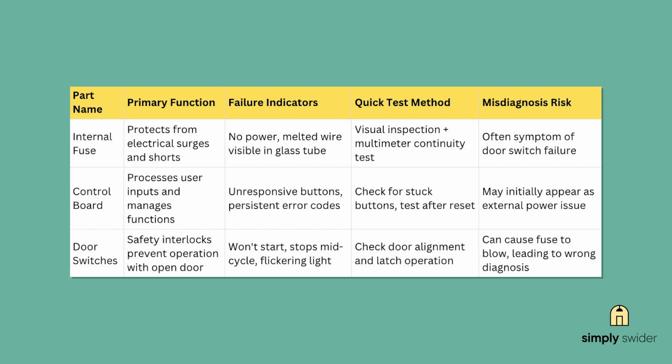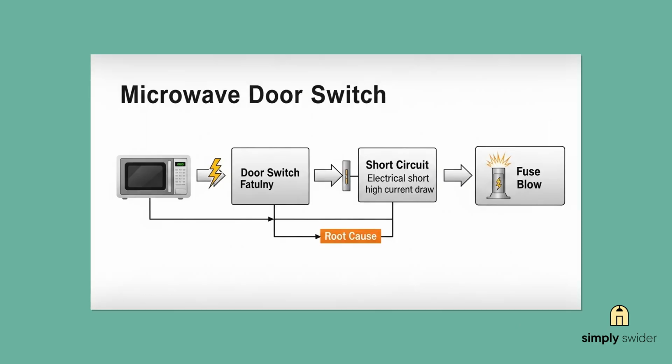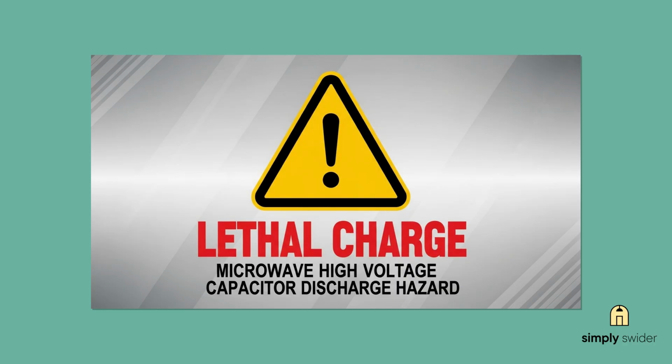The PF code stands for power failure. It means your microwave detected a power disruption. This could be a simple external power glitch that takes 10 seconds to clear or a more serious internal component failure. We'll start with the easiest 30-second fixes first, then move to repairs that might take an hour or more. This systematic approach will save you time and avoid unnecessary work. Trust me, we'll get this sorted out.